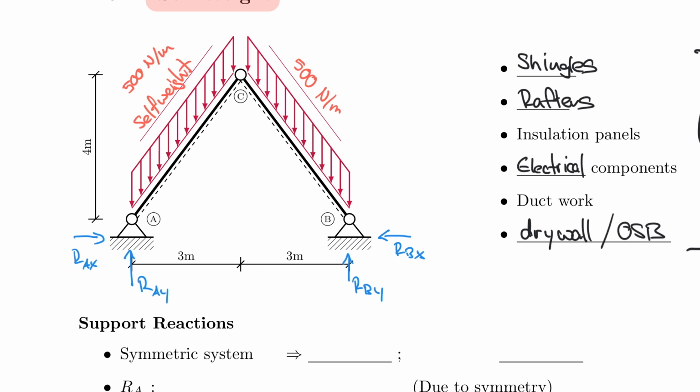And so it is very common initially to overlook the X components. The vertical is clear because everything that goes up has to come down. So these two balance pretty much everything that comes down. But because of the hinge here, if these were rollers, you can probably imagine that they would just slide out. And therefore we need something to prevent that. So we need RBX and RAX.